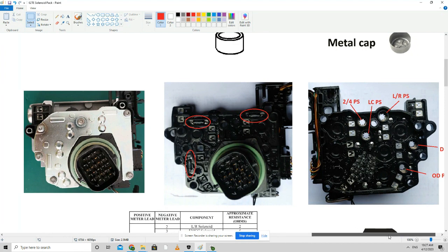This is the solenoid housing, as I told you. This is the metallic housing under which the springs reside. In fact, the switches reside in these pockets: 1, 2, 3, 4, 5. This is where the springs reside, and they get a ground from this particular plate. If you open this, what you'll see is that right underneath it, you'll see these holes: 1, 2, 3, 4. I can't see the fifth one from here. But anyway, you can see them clearly here.